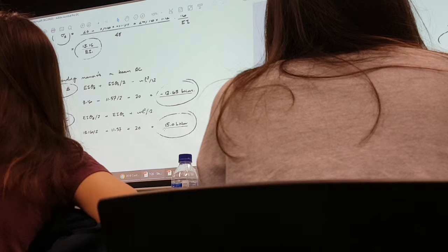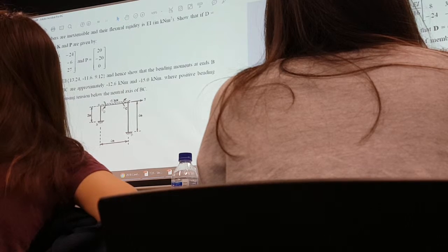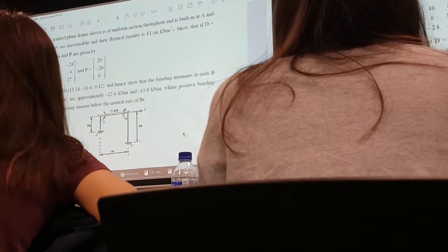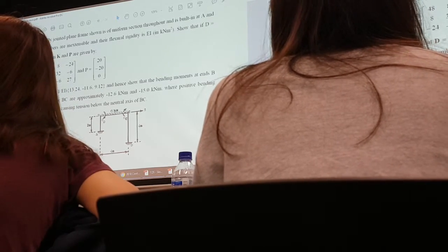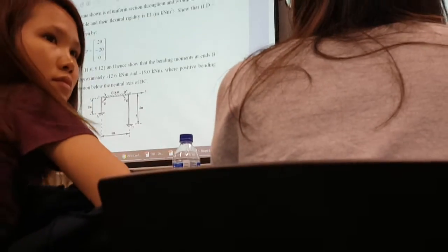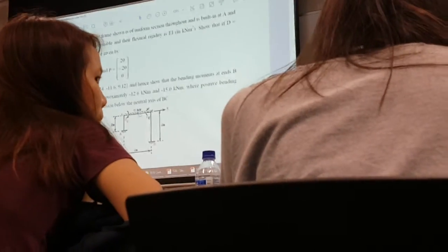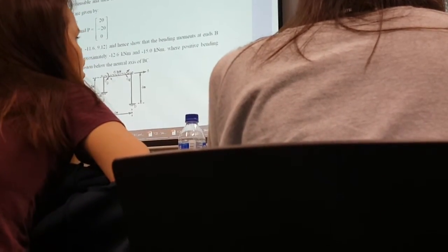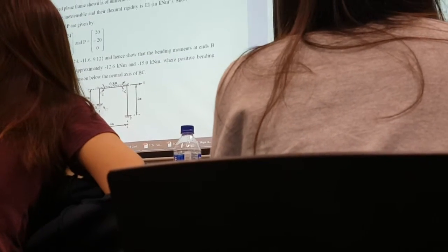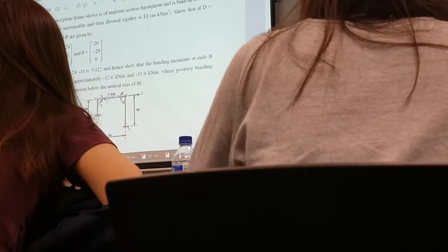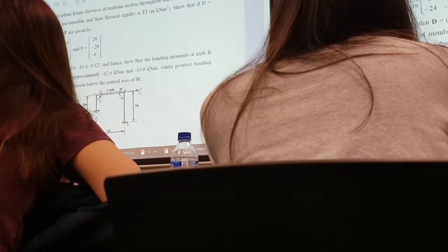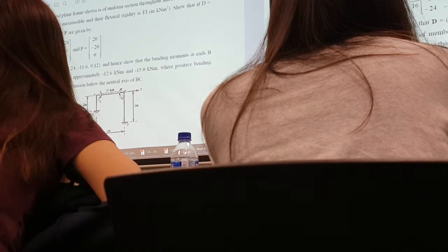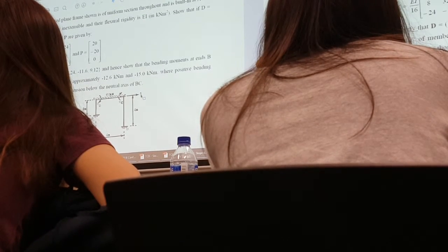Alright? Okay, so you can see for this case, example 2, it is really a more intensive question. First thing is that it gives you the structure, and it then has a uniformly distributed load. And it's telling you that because of this loading condition, it induces a rotation at node B and at node C. And also there's a horizontal deflection movement, a value of delta.